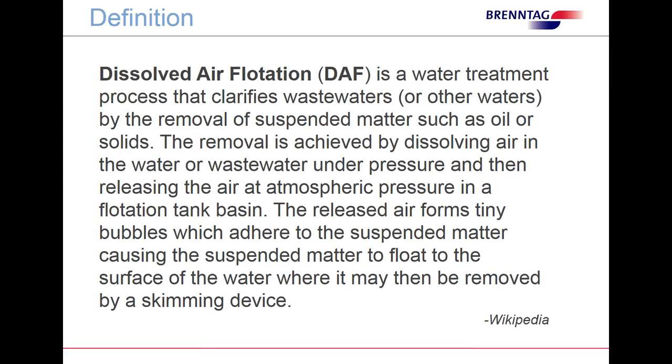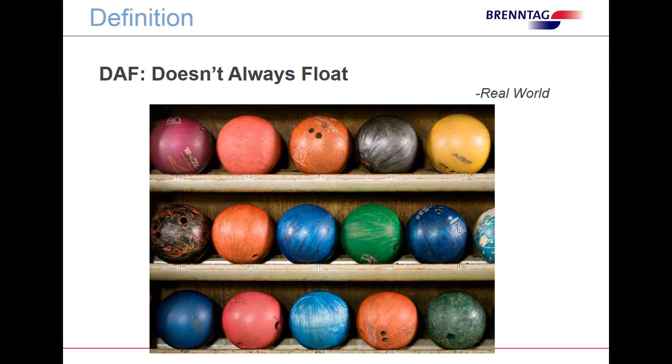So when we were putting this together, we were kind of joking around that DAF also can stand for doesn't always float. And it reminded me of an application very early on in my career where I was actually called to go into a bowling ball manufacturer who was having problems with a DAF unit. And one of the final steps in manufacturing of bowling balls is to polish the bowling balls. And when they polish it, they get fine particles that come off, and they run that water through a DAF unit,